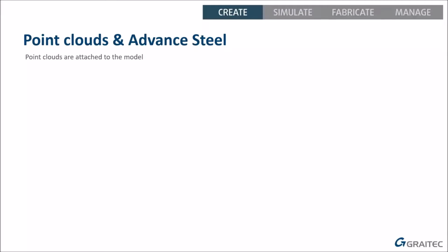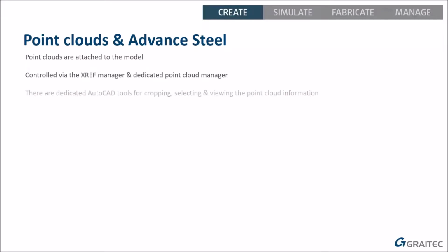Point clouds we attach to the model the same way that we would do an XREF, so it's no different than the way some of you are working currently. There is then a dedicated Point Cloud Manager, and there are some good little functions in there. The functions you see with the Point Cloud Manager are dedicated AutoCAD tools. Advanced Steel is built on top of AutoCAD, so we can take advantage of those tools.